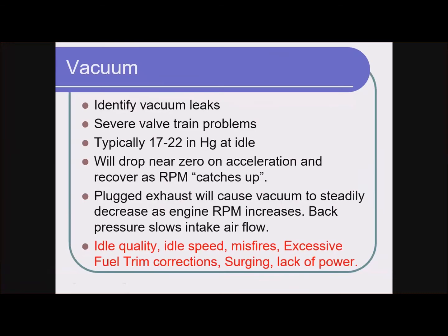If the vacuum never recovers, this is a classic symptom of a plugged exhaust, which could be a plugged catalytic converter or anything else. What will happen is the faster you try to make that engine run, the worse it will breathe. The exhaust is blocked. It cannot get rid of the exhaust. It cannot take in new air. So you'll see an engine that has good vacuum at idle, potentially. But then as you raise the RPM, maybe you go to 2,000 RPM, 2,500 RPM, the vacuum just starts to go away. The needle starts going closer and closer to zero.